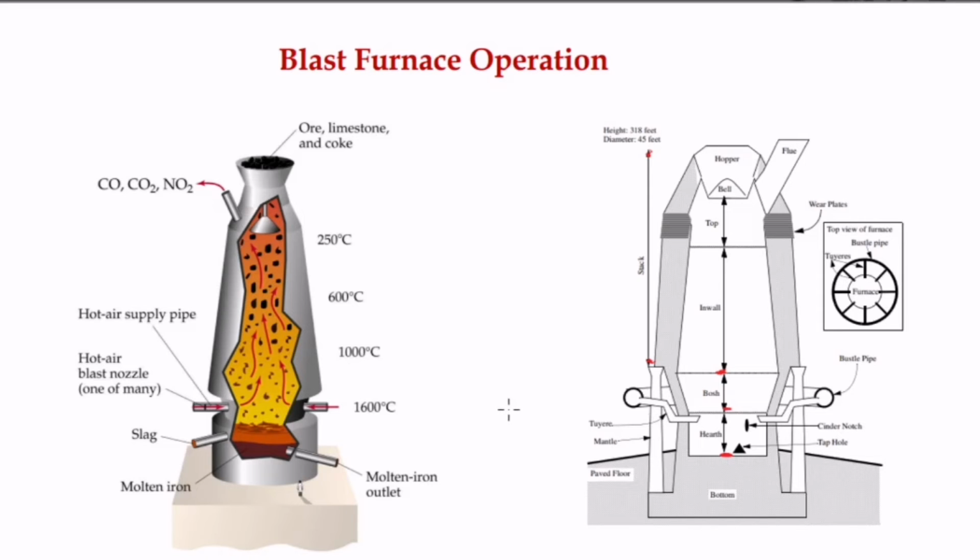So let's look at something in the blast furnace. We are talking about the stack. In the blast furnace stack, there is what? A counter current flow of gases and solids. In the stack, hematite or magnetite is reduced to what? Sponge iron by the action of what? Carbon monoxide. So in the stack, the gas is introduced through the turret and comes up, and the ore is placed inside and comes down counter currently, right? So a reducing agent, carbon monoxide, is formed, and this reducing agent reduces the iron ore, which in this case can be hematite or magnetite. So reduction happens at the stack.